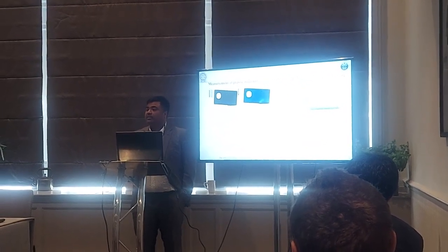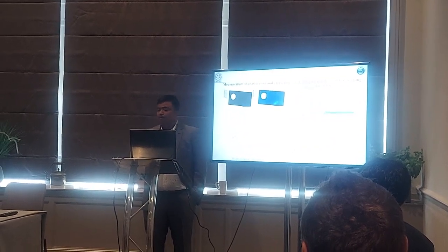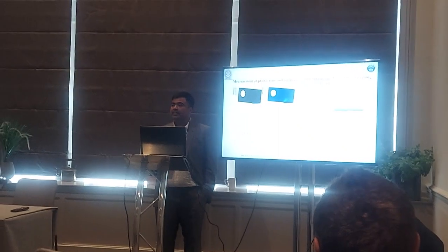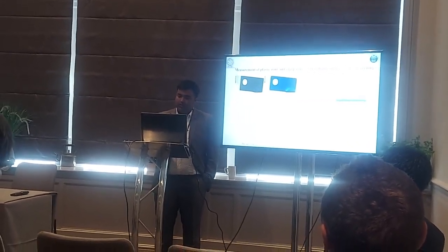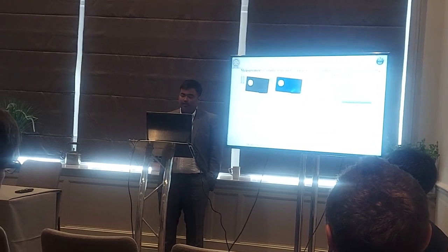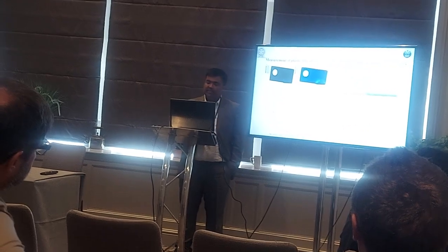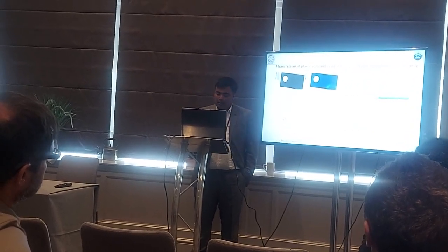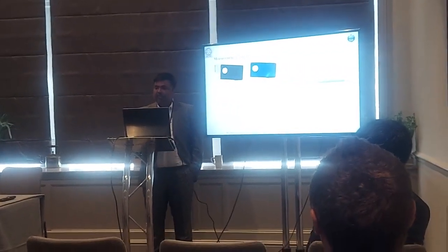It shows that the CT is path independent. But the configurational force result dJEP by dt, for the different contour values like 4 mm, 6 mm, 8 mm, 10 mm and 22 mm, is basically path dependent. So this is dJEP by dt very near to the crack tip.